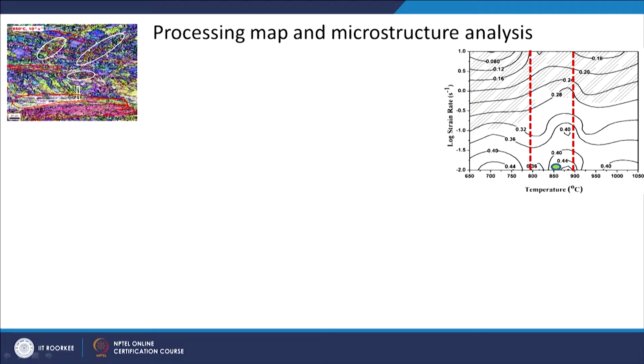Okay. So, we wanted to know whether any particular phase is responsible for this kind of behavior. The only problem is that in these kinds of alloys, when you do cooling, everything again gets transformed to one phase. So, if you are in the two phase region, alpha and beta, maybe alpha is doing something, beta is doing something, but you cannot preserve what beta was doing and what alpha was doing, because when you do the cooling both will have alpha phase only. So, both will look very similar.